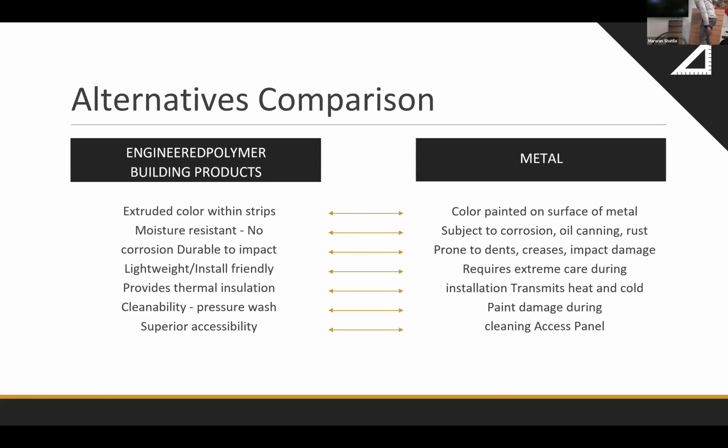This is, like I demonstrated, an assembled panel system. So assuming you had, if this was on the ceiling and you had a light fixture right here that you needed to do some maintenance on, or you needed access to the plenum for whatever reason, you don't need any special tools. You will just need a putty knife that you're able to source from your local hardware store. So you don't have to hire specialty contractors to come out. This is something that maintenance people can do at a facility. And essentially, you just have to tuck it in to where the carrier is and pop it out.